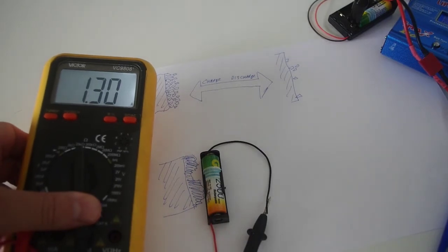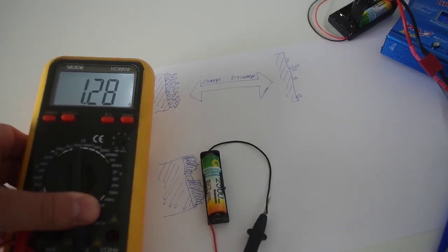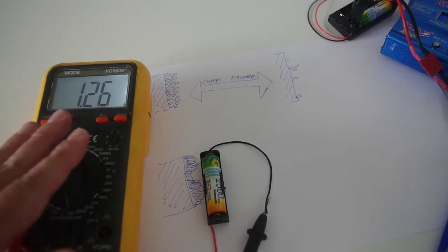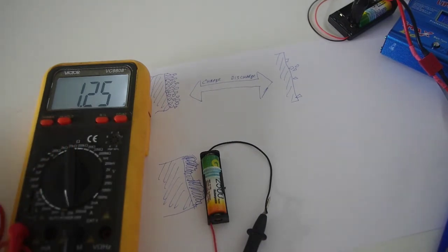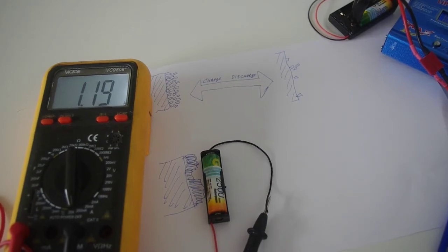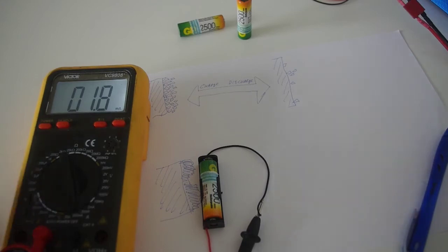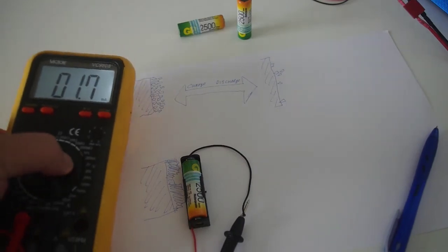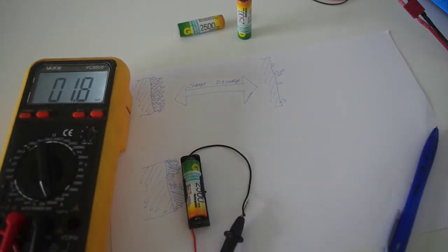So as you can see, there is some current, and it will quickly decay to almost zero, and you will need to leave it like that for 10 or maybe more hours until your current drops below 5 milliamperes or 3 milliamperes or so. So you need to wait, and you need to repeat this process for all 4 cells. And after almost a day, current for this cell has dropped below 2 milliamperes. So I think this is enough for this one.